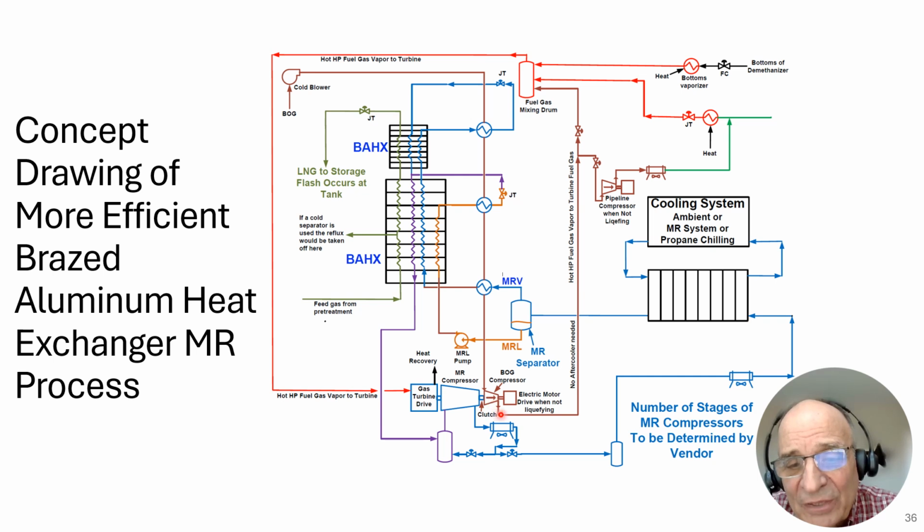Let's see what else is happening with the gas that comes off this boil-off gas compressor. Well, it goes to a pipeline compressor, because your pipeline might be operating at 1,000 psi. We don't have 1,000 psi here, so I have a separate pipeline compressor going out to the pipeline. And once you come off a pipeline, you're going to go through a JT valve. You want to heat that gas up before it goes through a JT valve because it will see a temperature drop as it goes across that valve, and you don't want freezing gas in here.